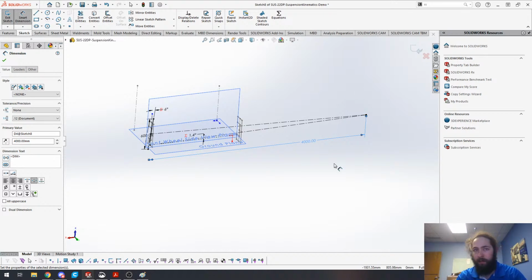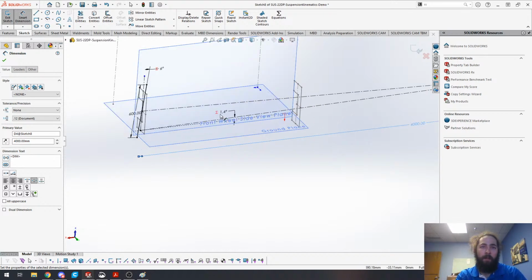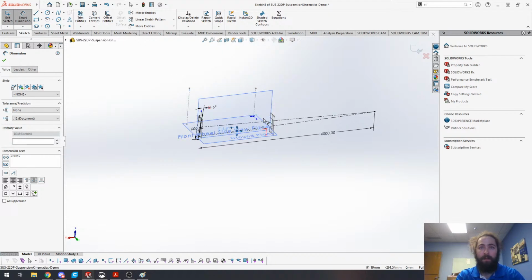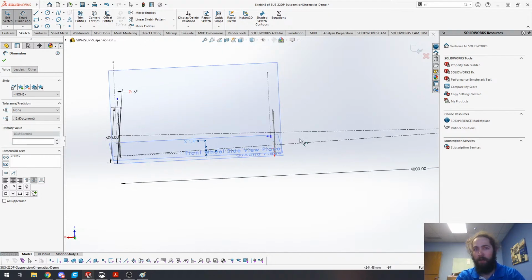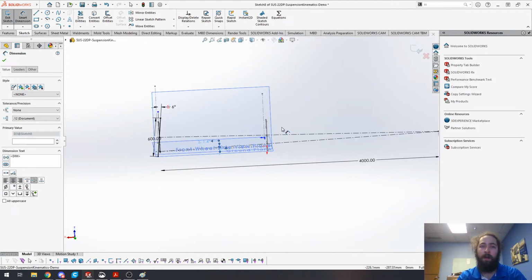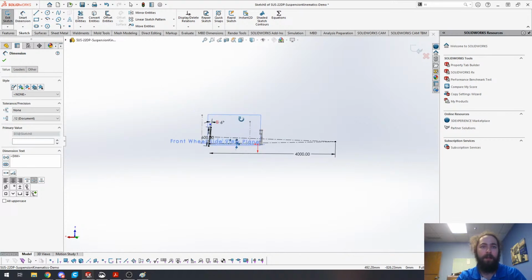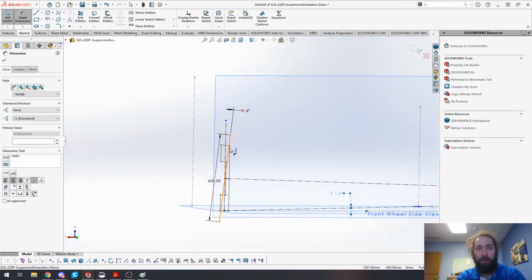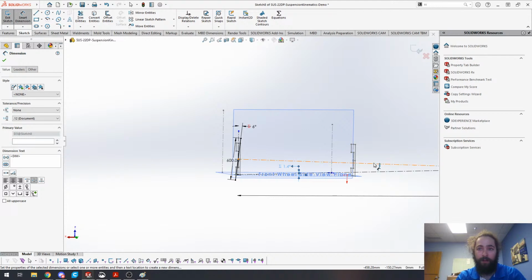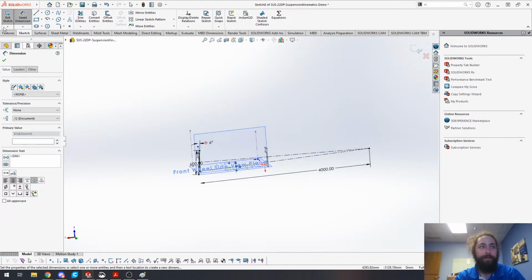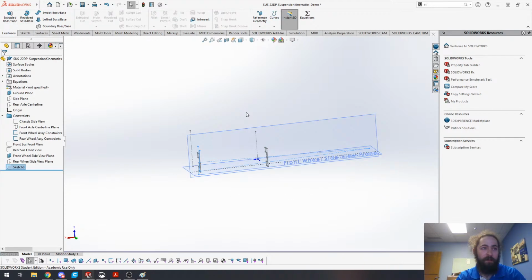There's some literature out there on it. But again, we're defining this based on what we want. This phi is based on our anti-lift properties. And then in the rear, we'll have both anti-squat and anti-lift defined, since that's our driven wheel. And then, of course, we also set up our angle here for our caster, our static caster. Cool. So pretty simple sketch.